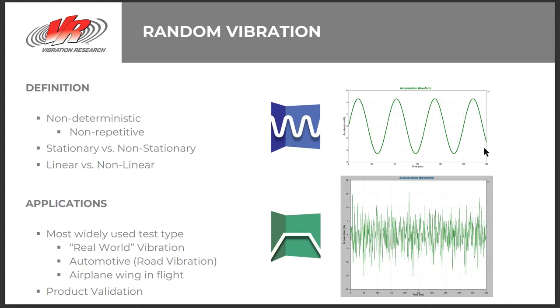In the case of a random vibration test, our random vibration is very stationary. So what does that mean? It is stable random. If I am running a 5 to 2 kilohertz 2Gs RMS test, the overall amount of energy averaged over a period of time will be what? That's 2Gs RMS. It will be very, very stationary. A non-stationary test has energy shifting rapidly back and forth throughout the test.